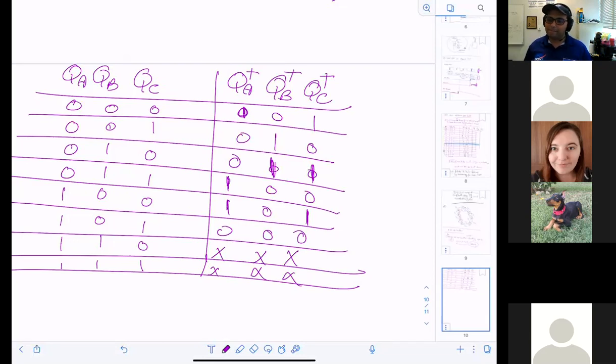Did you see what I did? I will never see 6 and 7, right? They are not in my consideration. I don't care about them. So some people will put zeros, some people will put 1, whatever they want. But at the end of the day, it's better for me to be tricky and put don't care, so I can find the best way of making an optimized implementation using fewer resources on the chip. Do you guys agree?